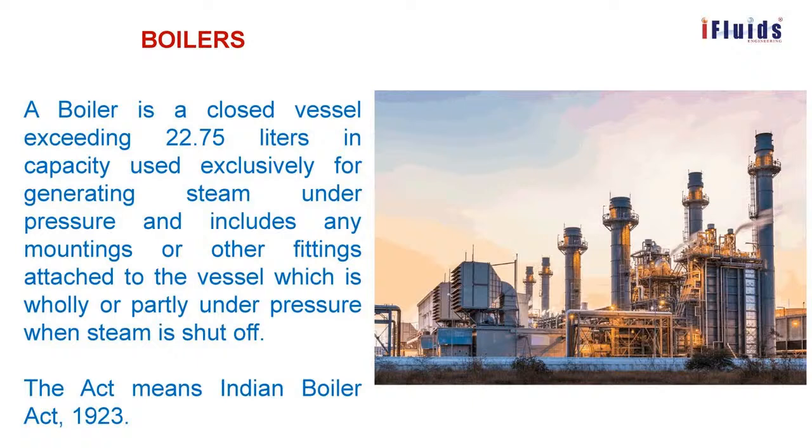So what is a boiler? OISD norms give a definition: a boiler is a closed vessel exceeding 22.75 liters, exclusive for generating steam under pressure, and includes any mountings or other fittings attached to the vessel which is wholly or partly under pressure when steam is shut off.